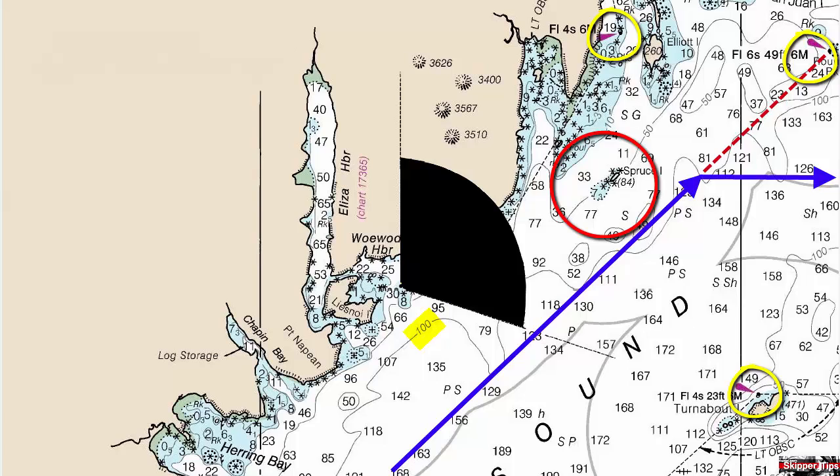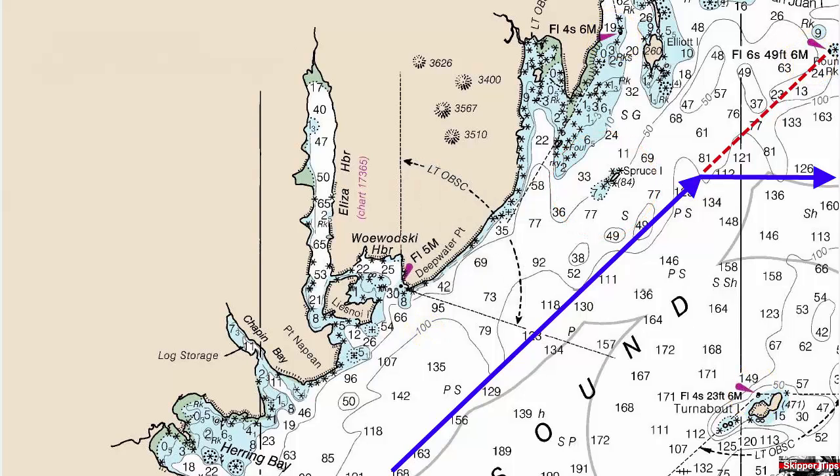Determine the point along the sailing track where you stop steering on the head-bearing light and change course. Set a waypoint at this position, or we could use a turn bearing such as the flashing white 4-second light to port. Use these easy sailing tips to help you evaluate a chart for sailing or cruising in piloting waters.